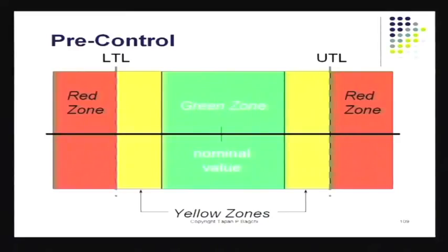and let at least a sizable production take place, which could be like after an hour or after maybe a shift or something like that, to collect the next sample. If you do that, you'll maximize the visibility of the assignable causes, and you'll make sure that the base variation, which is due to the chance causes only, that also is apparent and is pure. Within a sample, you only see what we call chance variation. So just go into this a little bit with your statistics, with your SPC book, and you'll be able to probably pick up the thing.